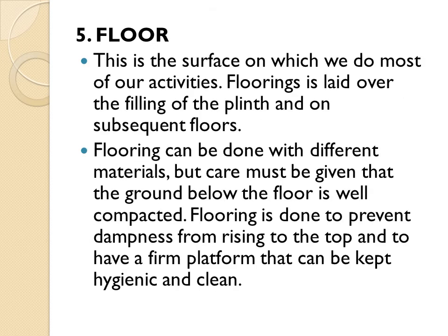So after the plinth beam, comes the floor. Now the floor we are discussing comes under the superstructure of the building. This is the surface on which we do most of our activities. It is a plain, horizontal and hard surface that is provided for the placement of furniture and for the movement of people. Flooring can be done with various materials, or we can call it a floor finish, but care must be given that the ground below the floor is well compacted.